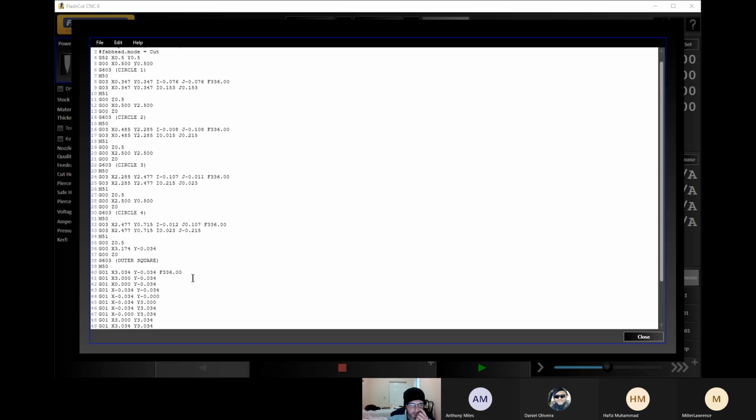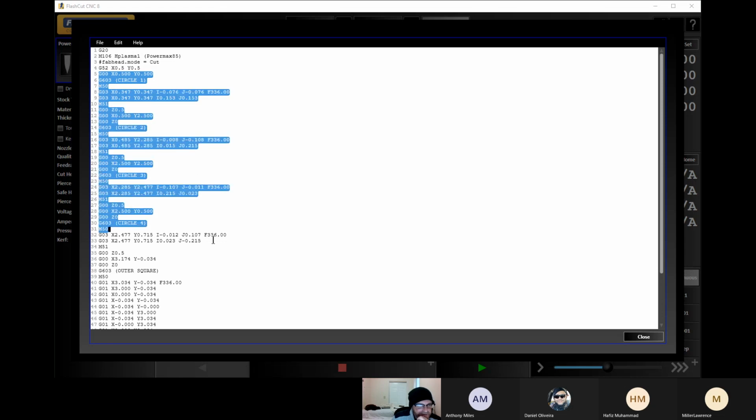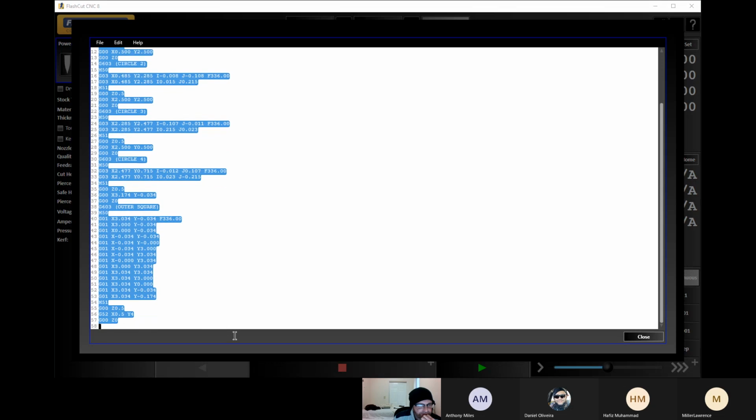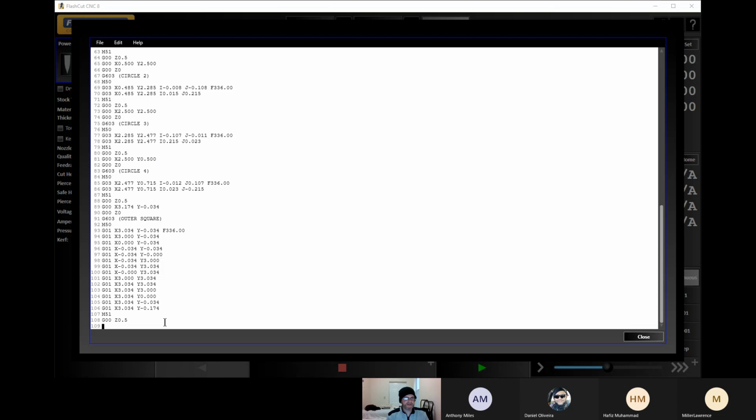Now watch this. We're going to take everything from line 5 and copy this entire program up until this G52 before we get to the next one. So we highlight everything, hit Control C to copy it. Line 58, we're going to hit Control V to paste it.